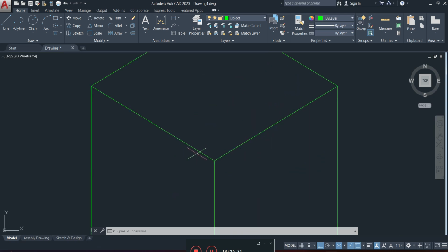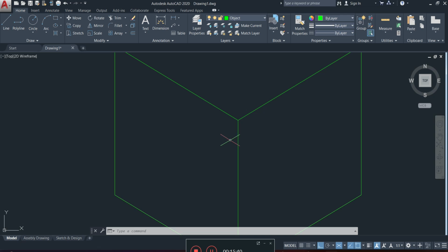Say for example I want to chamfer this in here. Now you have many options. You can fillet it using a radius and it will work fine, or you could utilize the circle function as well. So say for example that is 50, and I want to have a curvature here of say 15. What you can do, and this goes for any circular object, is that in order for you to place a circle somewhere, you need to find out where the center of the circle is. That's one of the easiest ways to do things.